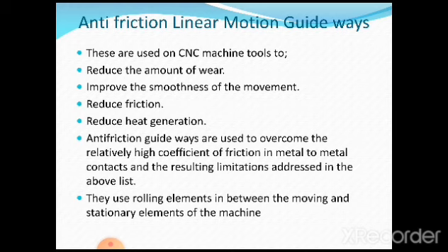This is a stationary element, and this is the moving element, which gives a linear precision motion for the mounting provided on this type of linear bearing with balls. Sometimes you can also have rollers provided, so such types of anti-friction LM guideways are used on automatic machines or automatic CNC machines.